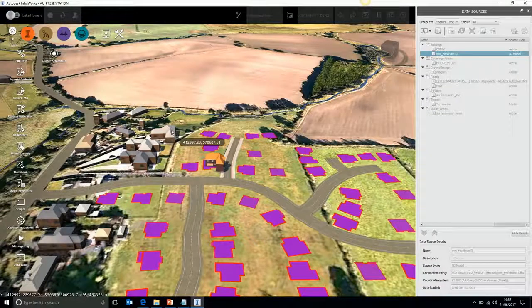you've got your InfraWorks tab immediately there in front of you. As you bring that in, you have full options to customize all your pipe networks. So if you wanted it to be sewers for adoptions, you can have all their line type styles, all their sizings. You can change everything else through there for you.